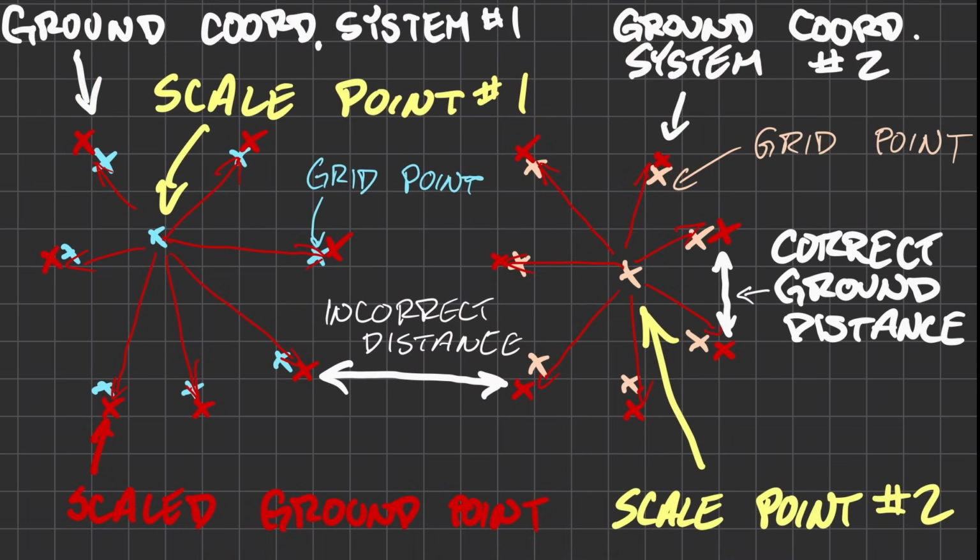This could change though. If you're working on the side of a mountain or in areas of large vertical relief on projects that require the highest level of accuracy over large spans, it's not unheard of to break up a project and use multiple scale factors. This would, however, be the exception, not the rule.